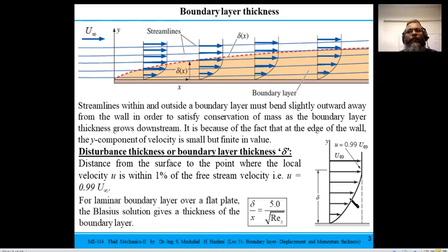And we already started right from the order analysis. We have the relationship that boundary layer thickness is directly proportional to x and inversely proportional to the square root of the Reynolds number, and from the Blasius solution this proportionality becomes an equation, and we know 5.0 is the constant for that boundary layer. So your boundary layer thickness you can exactly work out at any x once you know the Reynolds number. So at a given Reynolds number you have a certain boundary layer thickness.